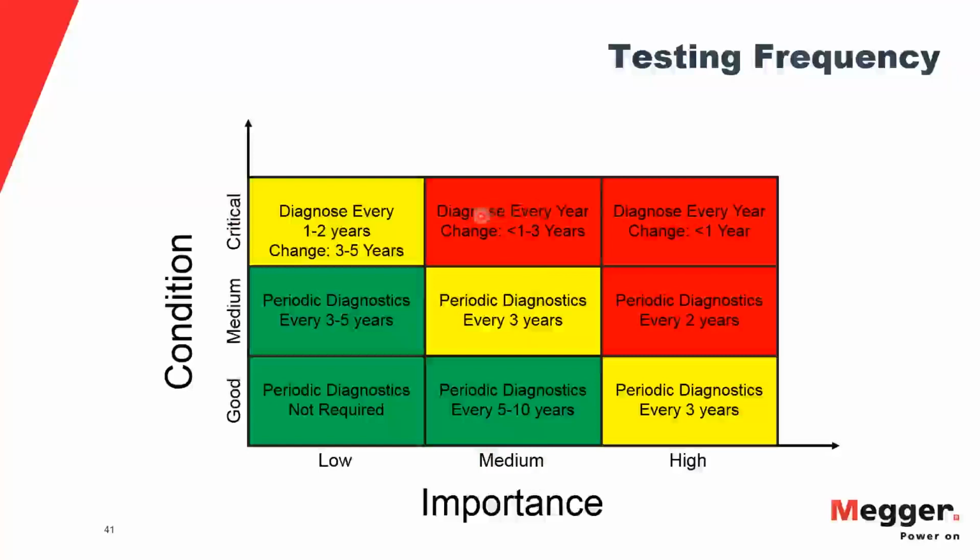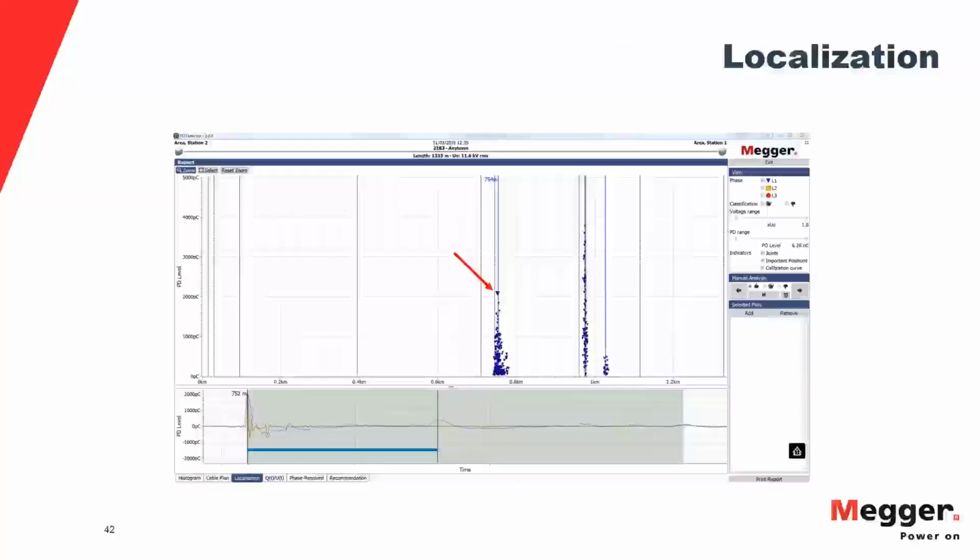When we have a partial discharge event in the cable, it induces a signal into the cable, and that signal travels in two directions. One of the signals travels directly back towards my receiver, towards my measuring equipment, and one of the signals heads towards the far end of the cable. Once this one reaches the far end of the cable, it hits the end and it bounces back, and starts heading back towards the receiver.